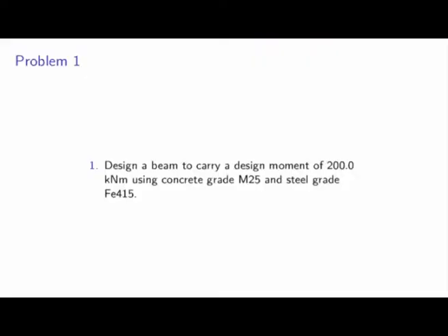So, design of reinforced concrete structures: let us see a few problems and then it will be clear what we are going to do. Let us consider the problem first: design a beam to carry a design moment of 200 kilonewton meter using concrete grade M25 and steel grade Fe415. So this is your objective. Now the question is, where did you get this 200 kilonewton meter from? Who told you that we shall use M25 or steel grade Fe415?